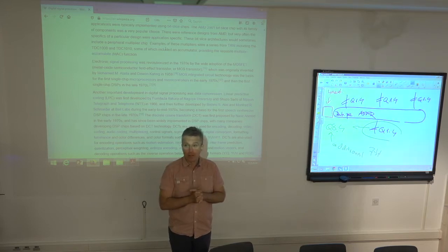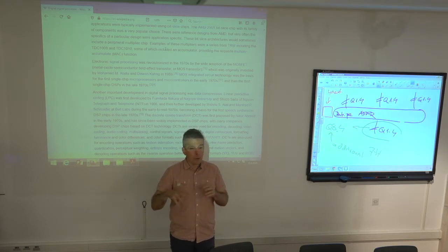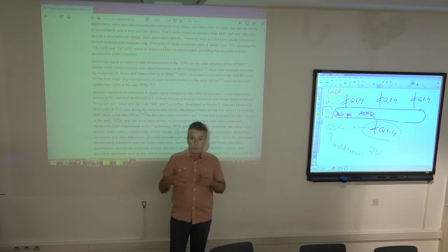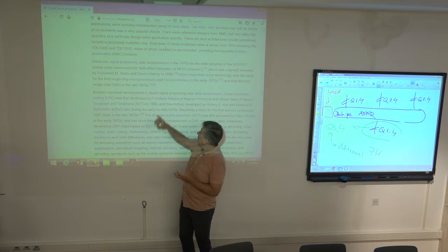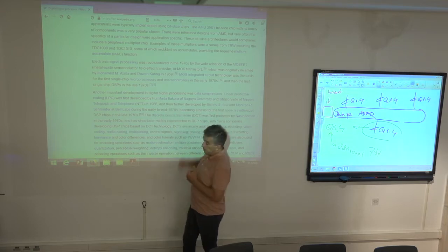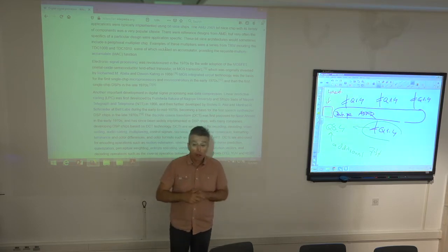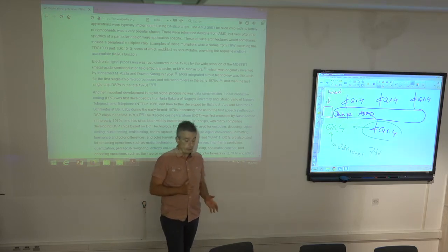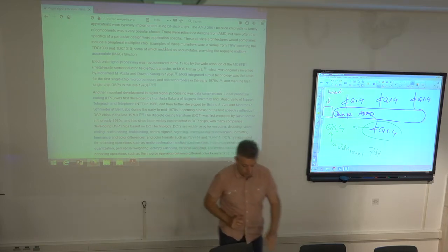This mobile communication system was limited maybe to 13 kilobits raw data rate or 19.6 kilobits if you include the channel code as well. And for that reason, the speech had to be compressed. The idea of this linear predictive coding, this LPC, was how to efficiently encode speech with a lower number of bits than you would have at the output of an AD converter connected to the microphone. So how to encode this information.